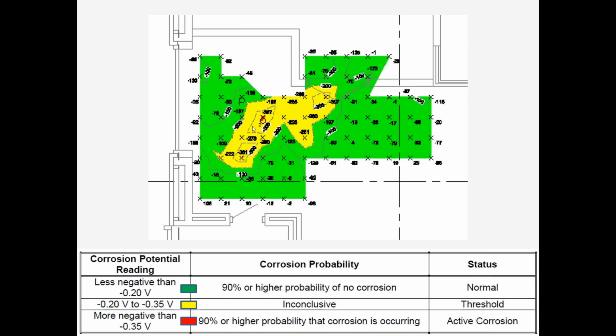The snow and the slushy, salt-laden snow would basically melt and collect. And this area right here was an area of high probability of active corrosion. And we could see it from underneath. Also, there were some visual signs underneath. There was some delamination, no spalls on the top surface, but there was some delamination on the top surface.